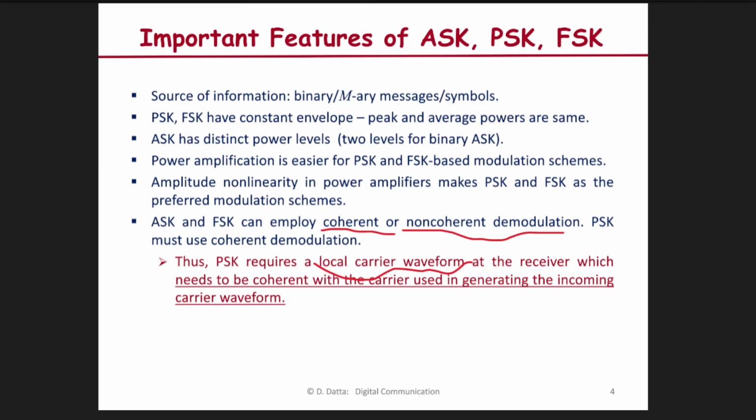The carrier used in the transmitter has to be recreated, so that it is in sync with the local carrier. The incoming carrier and the local carrier should be synchronized to each other to make PSK demodulation successful.